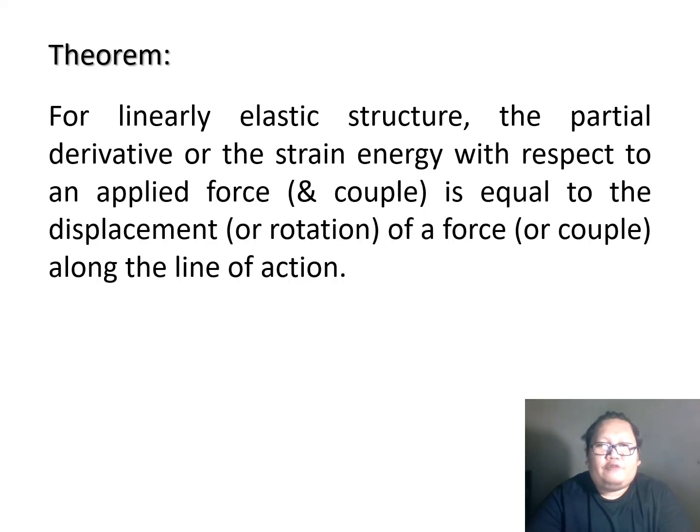Theorem. For a linearly elastic structure, the partial derivative of the strain energy with respect to an applied force or couple is equal to the displacement or rotation of a force or couple along the line of action. So it's actually just the same as the virtual work method, but this time we're going to partially differentiate the equation of a certain structure in which deflection and rotation or slope are being asked.